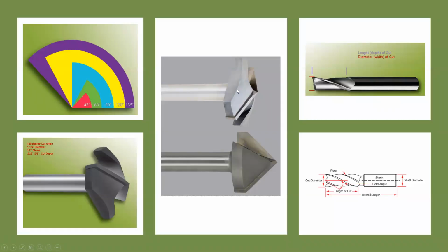You'll also need some specialized cutters based on the line weight that you want to have in your carved letter. Also, you'll need to consider in the angles the thickness of material that you'll be using. So here are several cutters. This cutter, for instance, is a 120-degree angle. So the beveled tip is 120 degrees from side to side. And we can see the yellow contour basically represents the carve profile that a 120-degree cutter would have versus a 90-degree cutter, for instance.